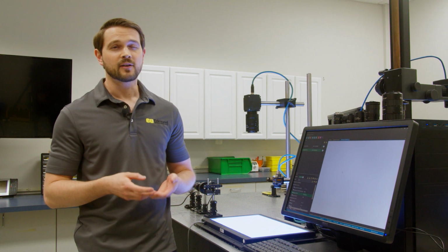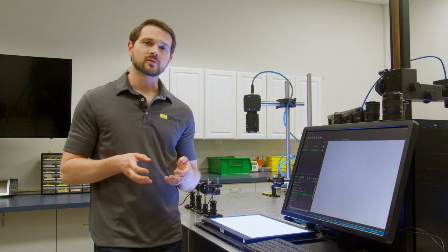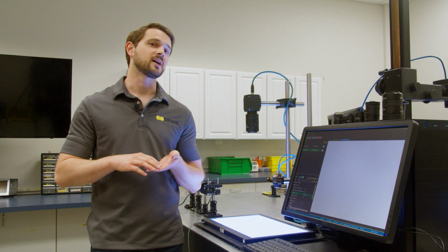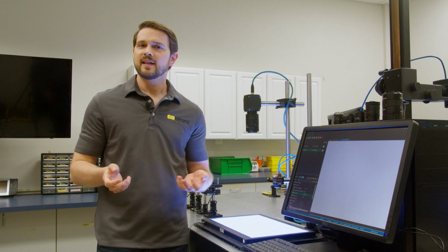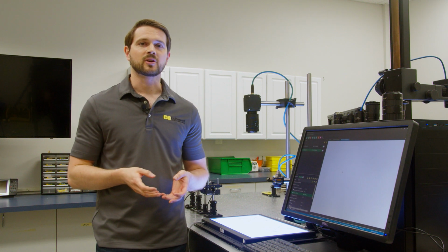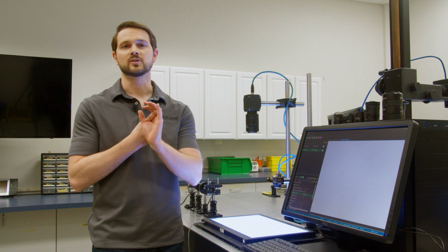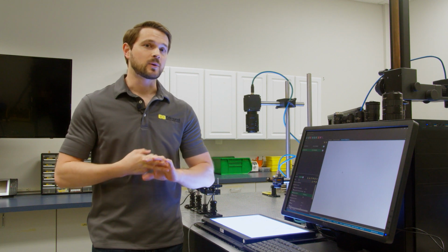field of view ratio of around 4:1, which means that if you're looking at an object that's about 100 millimeters in size, you're going to want to try to be about 400 millimeters away. That'll give you optimum system parameters, and it's going to make sure that your system functions in the way that you want it to in terms of costing the least while performing the best.